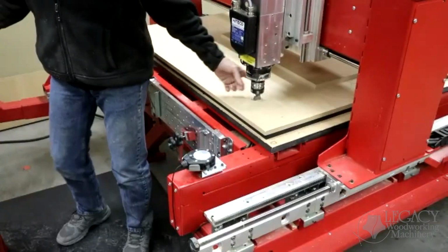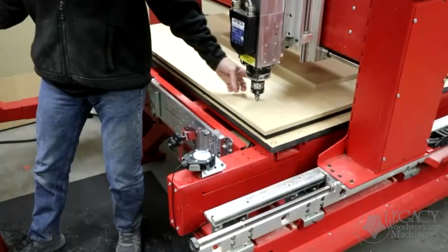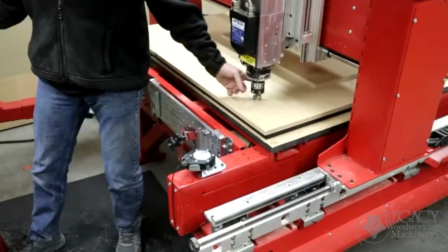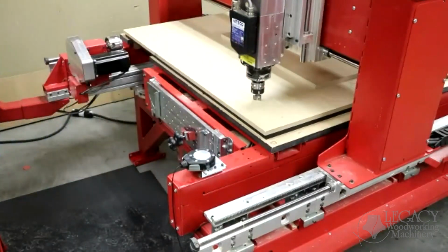I'm going to spin that cutter and just bump it down. Okay, so there I spin it, I can feel it. I can turn it, but it is touching the table at that point. So that's my 0 point. And we can set that all the way down, on the screen here, to 1/1000th of an inch. Okay, so if you want to get extremely accurate, which I normally do, once I touch it, I back it up 10 thousandths, then I step down 1/1000th at a time until it's just the depth that I want. It's got to be rubbing on that table.